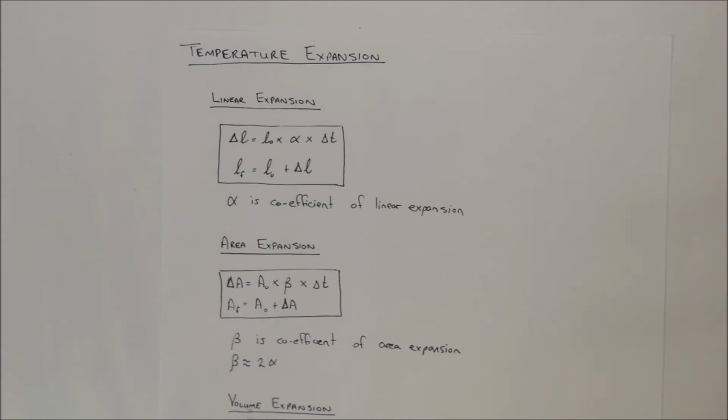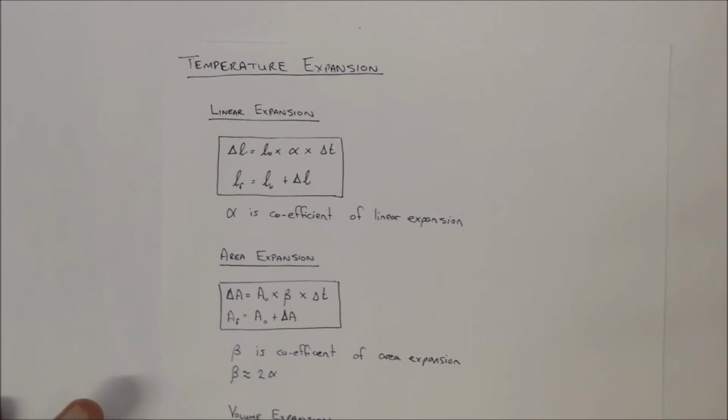So they hang a little bit, so there's some ability for expansion and contraction of the material. Those things need to be taken into account whenever you're doing your designs. It might be just a normal electrical cable, but if there's temperature expansion and contraction happening, it could cause it to snap, and you don't want that. So temperature expansion is quite important to keep in mind.